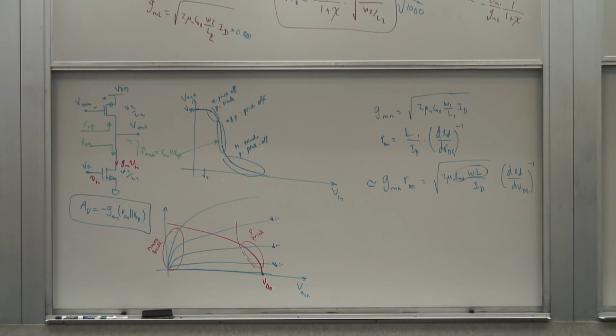It's the gate capacitance. Right? So it says, increase the gate capacitance, your gain will go up. But increase your gate capacitance, what goes down the tube? Yes, your speed. So there's a direct trade-off there.